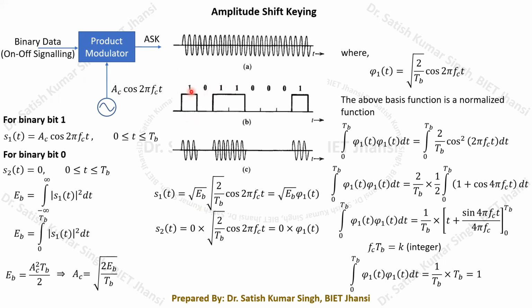Okay, so this type of waveform, this type of line code, is the only one used, remember that. It's not polar signaling, it is just unipolar, on-off signaling. In this case, whenever there is a binary bit 1, there will be a presence of pulse. Whenever there is a binary bit 0, there will be an absence of pulse for the bit duration of TB.